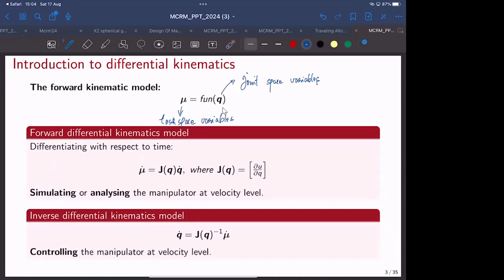For example, I'll give an overview for a 2R robot, comprising two revolute joints, which is why we call it a 2R robot. I'll label this axis as Z1, and the second revolute joint as Z2.